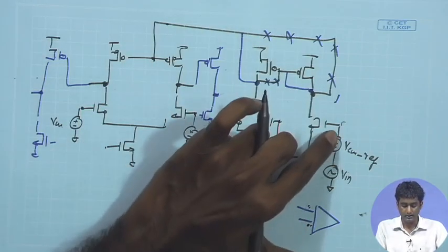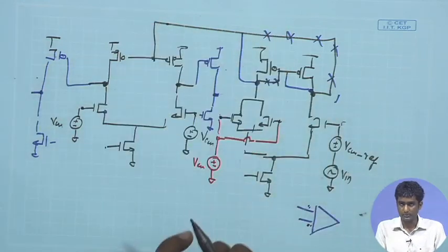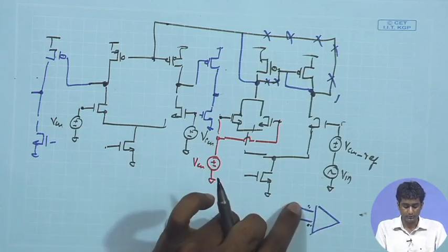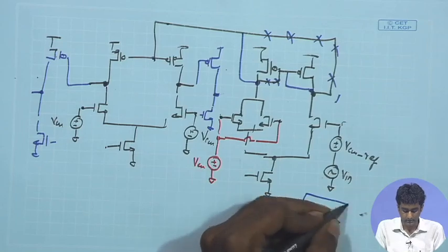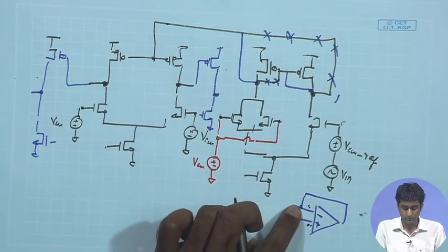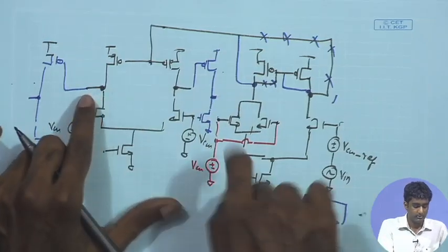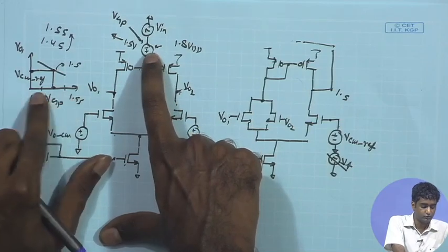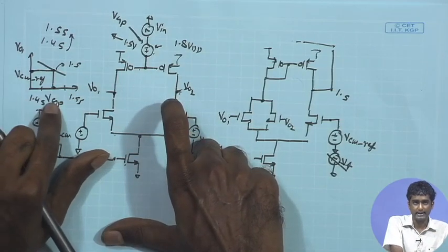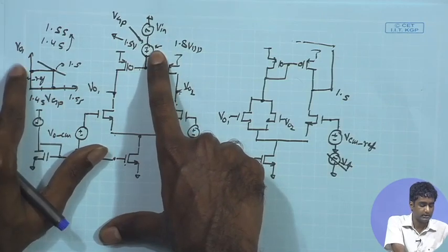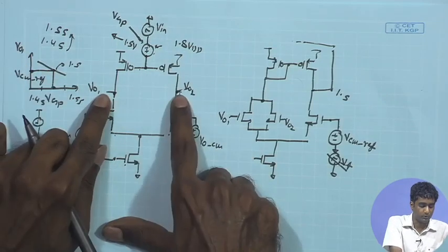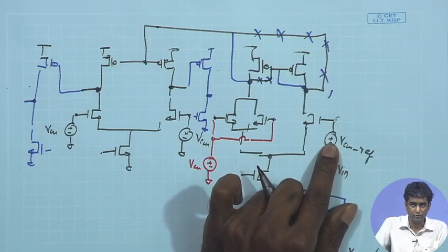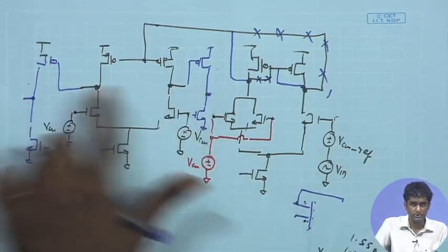Therefore, either you have to read the voltages very carefully. In simulators it may not show all the decimal places. So, if you want to get the precise value of the DC potential over here with the negative feedback, you need to do the sweep as we suggested over here. So, rather than choosing the exact VCM ref, you need to sweep it a little bit and then find the exact VGP in this case, to get the exact right value of the output voltage. And likewise, when you are opening the loop here, you need to maybe sweep this particular DC voltage, so that the output potential over here is equal to the required Vref.